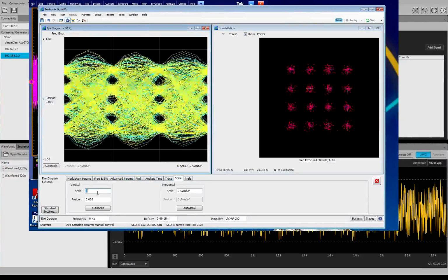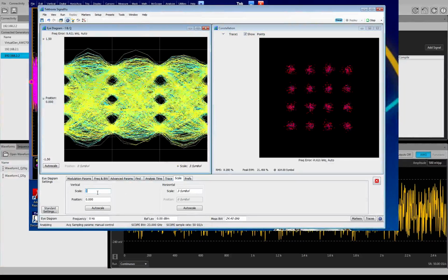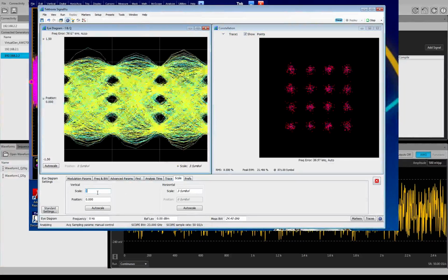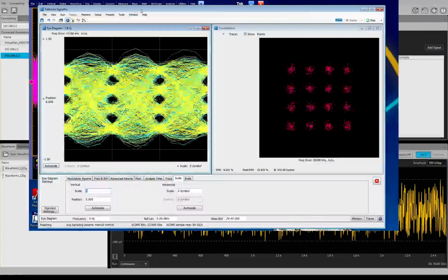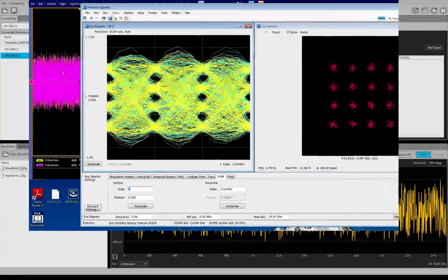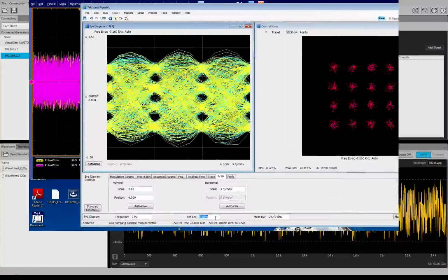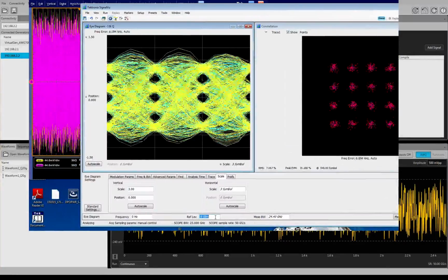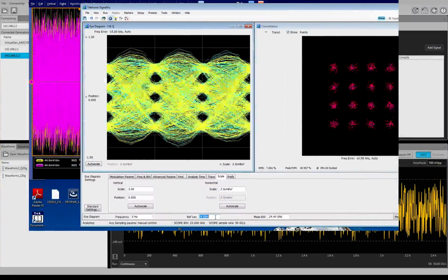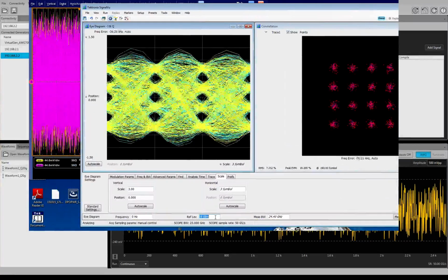So you can see that this is an uncalibrated signal, and you can see that the RMS EVM is like 8% and the peak is 2%. Some of you guys will realize that I'm not using the full scope settings here. So if I go down here and maybe put it like -8, this is probably the best I can get here. So we're looking at an RMS value of about 7%.